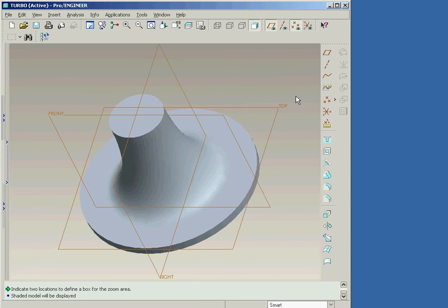We'll begin at a point after having created a revolved feature that represents the hub of our turbocharger fan wheel. We are now ready to create the first fan blade. The blade will be defined as a thickened extrusion, so we'll start by clicking on the Extrude tool icon.